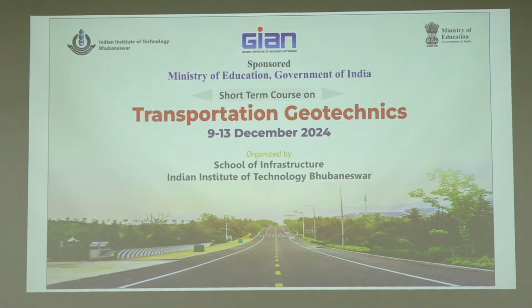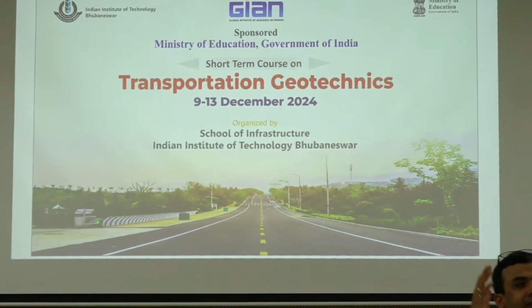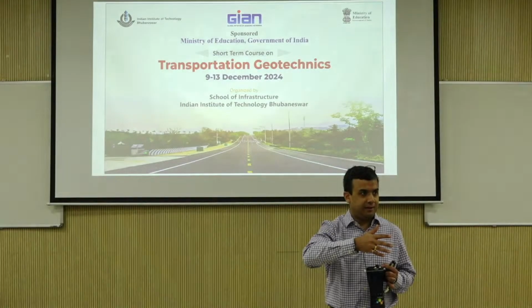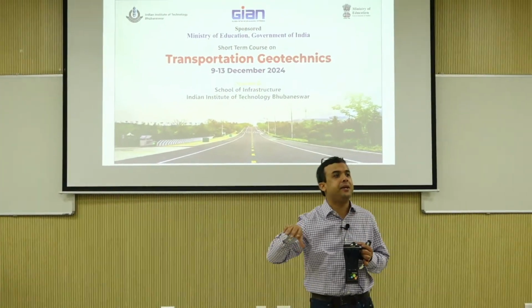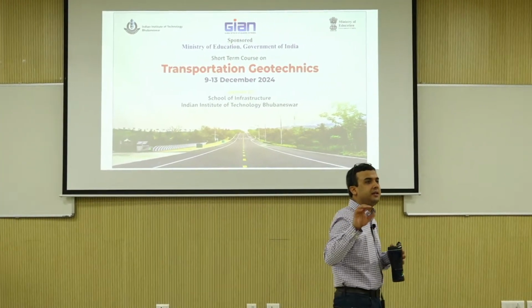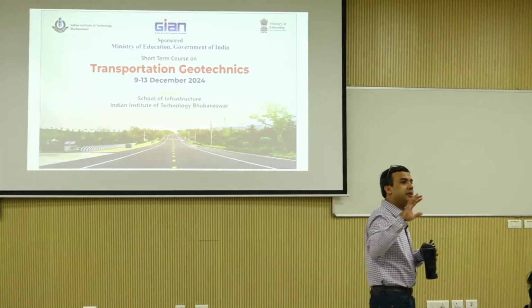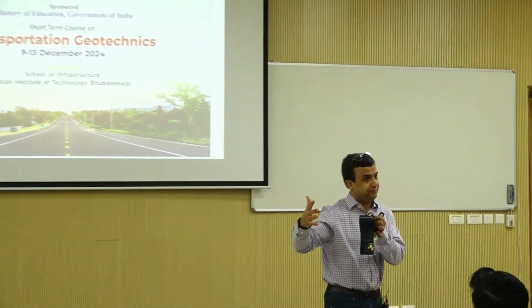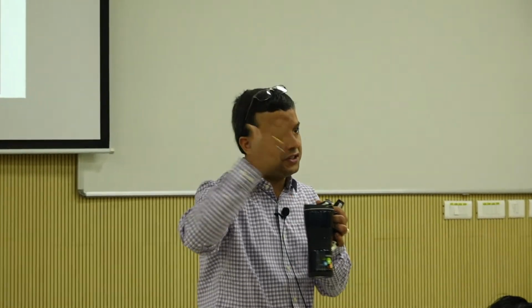Okay. So, good question. These are two different areas. PG grading and Superpave are based on the material, and mechanistic-empirical design, AASHTO 1993, and the Asphalt Institute method are all pavement design, right? The first one is how you select the cement, how you select the concrete, how you select the brick. The second one is how you build the house. Do you see the difference?